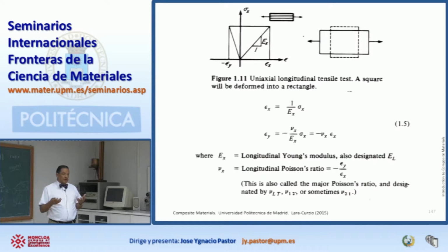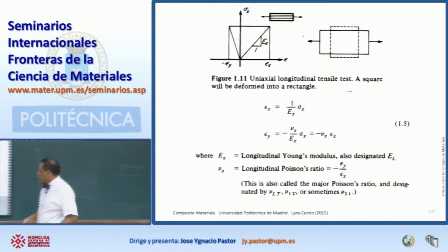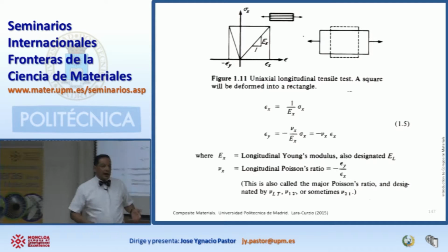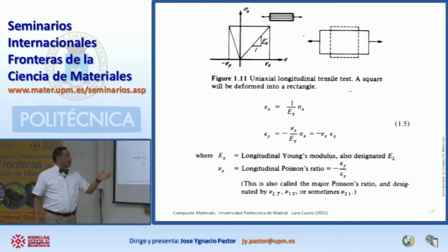And based on the type of stresses that you get, you say, OK, we've got to put 2 millimeters in thickness of the material here. We've got to put 1.5 millimeters. We can save some weight because the stresses are not so high. That's where it comes into the picture. The question is, how do you calculate those stresses based on the material? So what we're going to see here for the next few minutes is an overview of how we calculate stresses and strains in systems that are anisotropic. It's not different from the crystal. Okay? In the composite, the same thing happens.